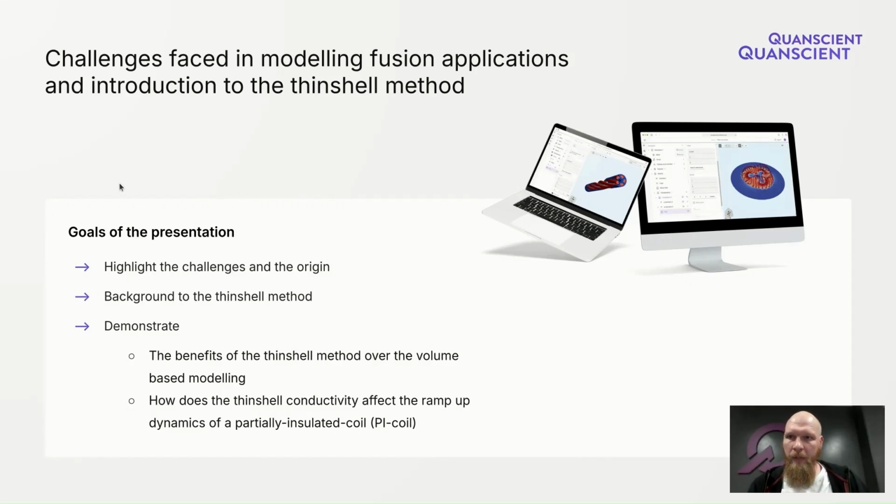Today I will talk about challenges faced in modeling fusion applications and give a short introduction to the Thinshell method we have implemented in AllSolve. The goals of the presentation are to highlight the challenges and the origin of those, give the background to the Thinshell method, and demonstrate the benefits of the Thinshell method over the volume-based modeling. I also want to show how the Thinshell conductivity affects the ramp-up dynamics of a partially insulated coil.